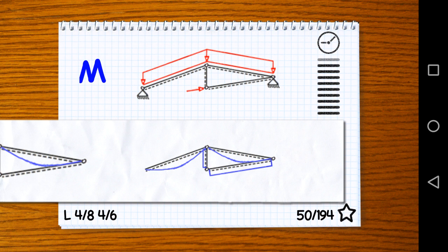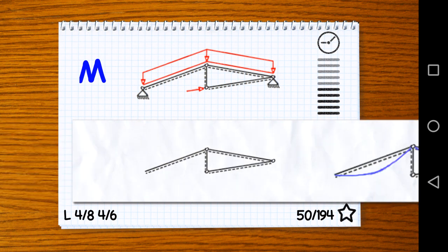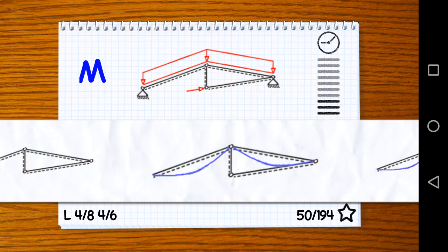The two rods that are connected there and subjected to a single load are rods, as I said already, so they can't have any moment. That's why this right answer here is wrong. The left answer here completely ignored the distributed loadings, so the right answer is here in the middle.